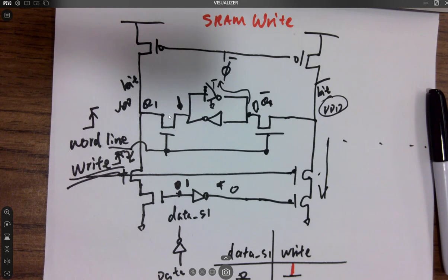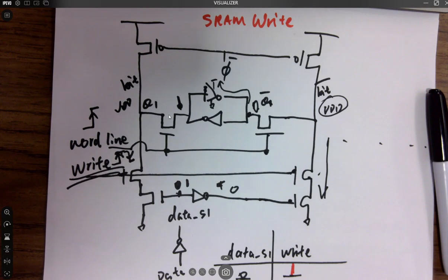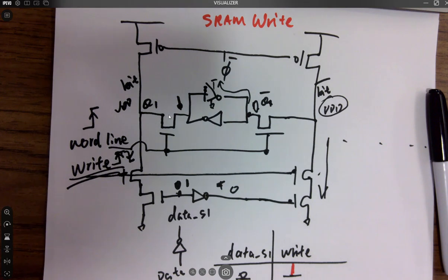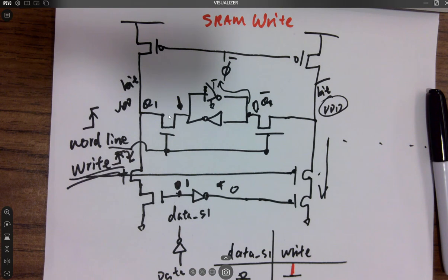Remember the one I showed you last time? The memory banks I showed you on the chip on Wednesday, right? The chip from Cadence, you have 2 memory banks, really long. And these are already a lot of memory, and you can see it takes a lot of space. These ones were actually designed by the memory compiler from the foundry. If you want to implement the same size of memory using Verilog and simply synthesize it using D flip-flops, it's probably going to be 20 times larger than that. And your chip won't be able to fit this much memory.